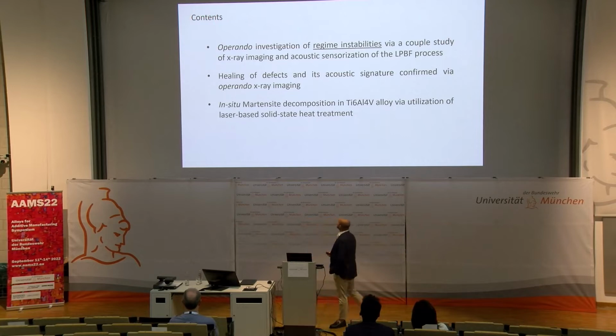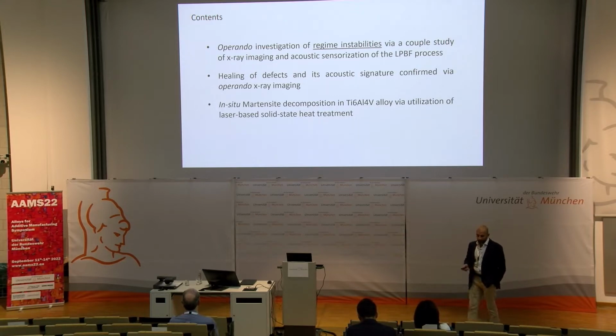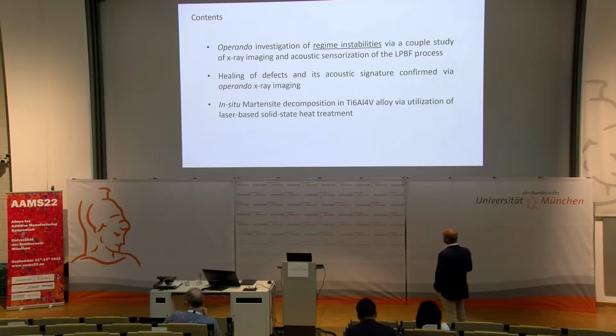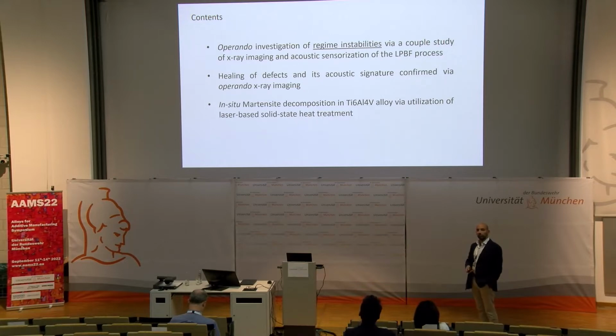Okay, it works. So my talk is going to be in three parts. It's going to start with Operando investigation of the regime instabilities under constant process parameters. This is the stochastic nature of the LPBF process, but we're going to see some nice work on that, and also the application of acoustic sensorization to somehow alert us, to some extent, when these instabilities are occurring, because you don't want to have an unstable keyhole while you optimize your parameters for staying in conduction, right?